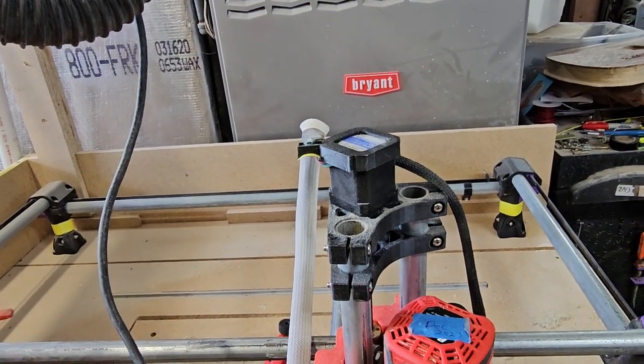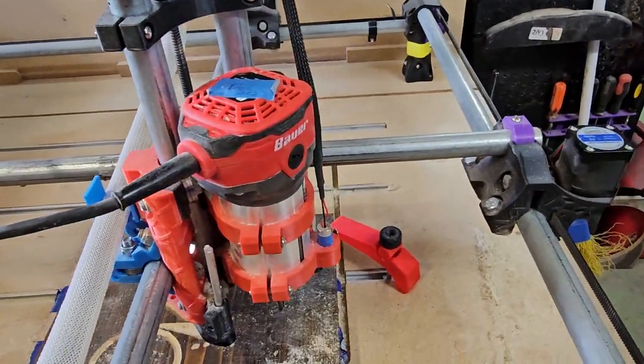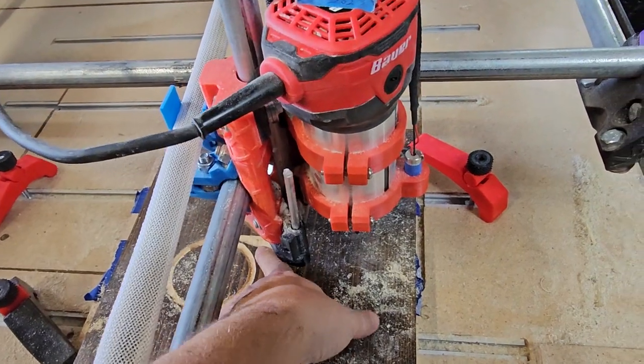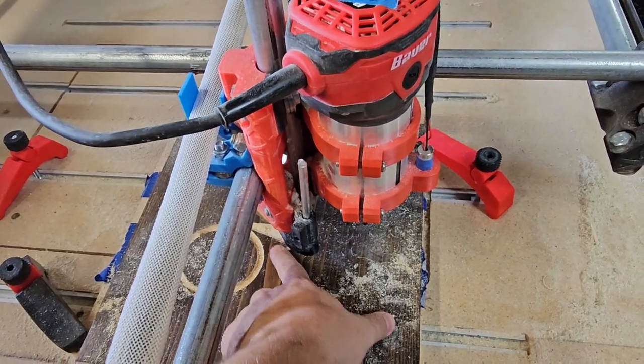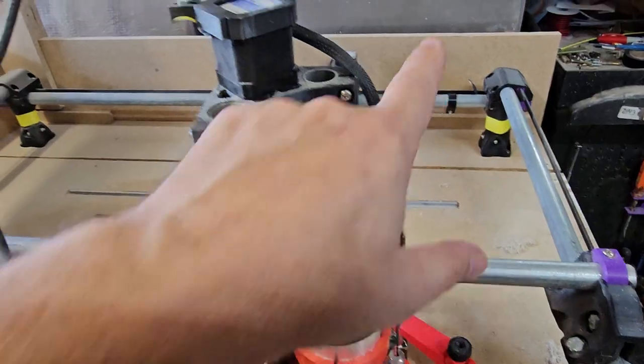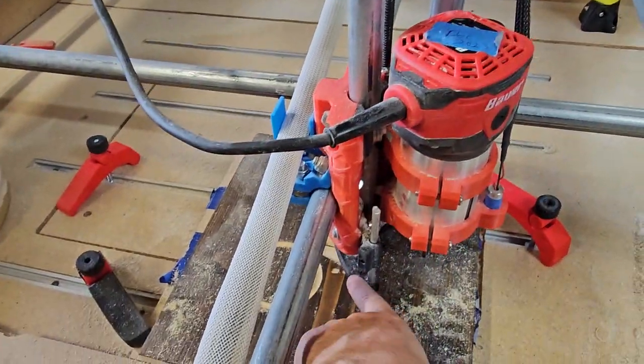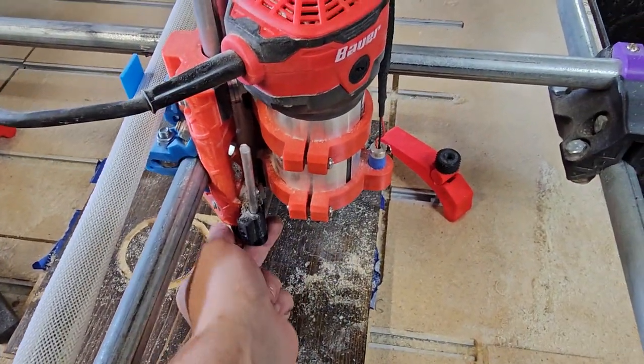After that, we've got our X, our Y, and our Z. Even though I move this, it remembers exactly where that 0, 0 point is, so everything's going to index that no matter where I run this machine on the table. That point is 0, 0 until I tell it otherwise.